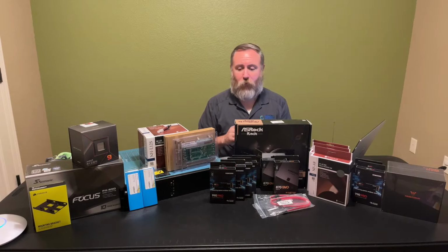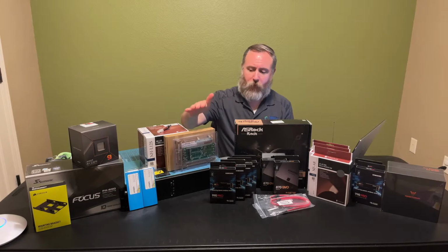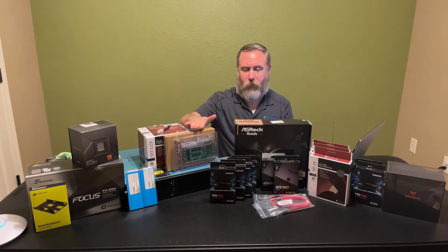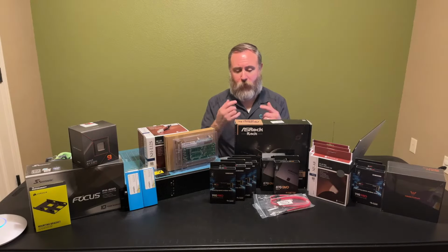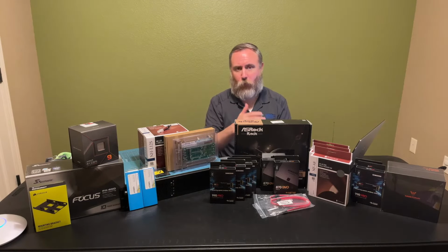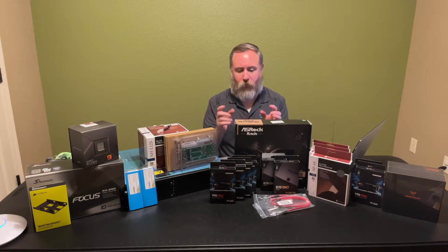That's something you may not be aware of, but if you buy one of these riser cards that says it needs bifurcation, you've got to make sure your motherboard supports that. It's a BIOS setting. You go in there and change the way that 16x PCI Express slot is laid out, and you say you want it divided up into four 4x lanes.